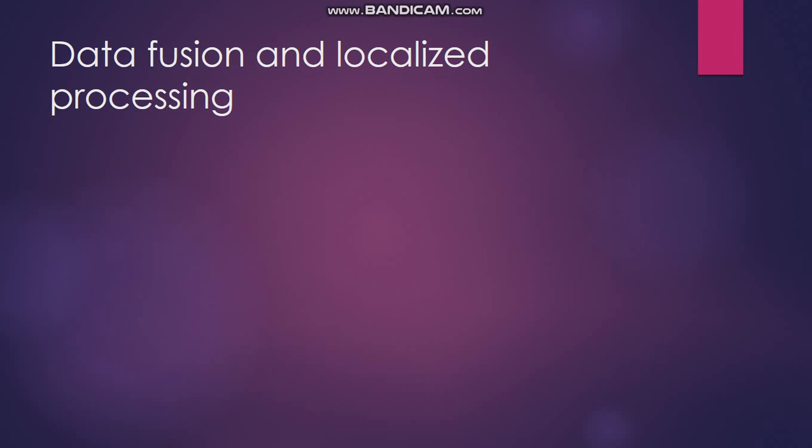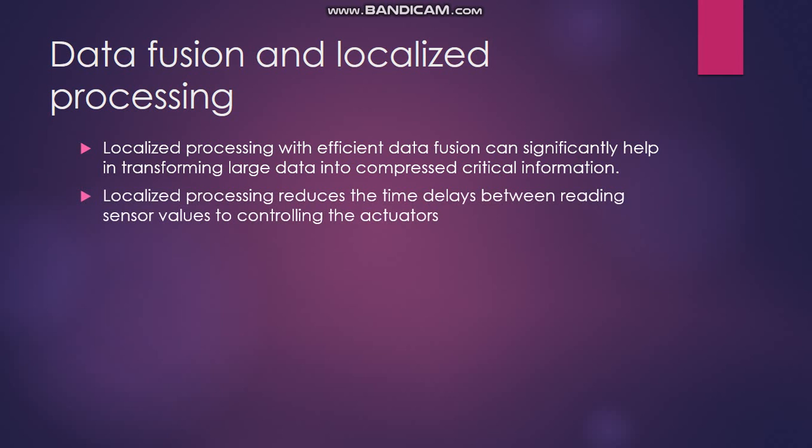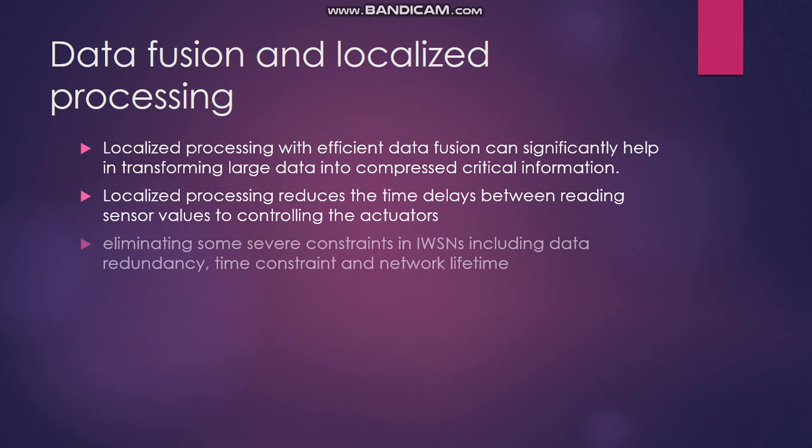Data fusion and localized processing. Data fusion is an essential aspect of IWSN and can be hugely beneficial in harsh industrial applications. Localized processing with efficient data fusion can significantly help in transforming large data into compressed critical information. Localized processing also reduces the time delays between reading the sensor value and controlling the actuators. If efficiently implemented, this process can help in eliminating some severe constraints in IWSN, including data redundancy, time constraints, and network lifetime.